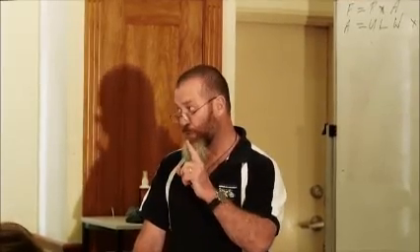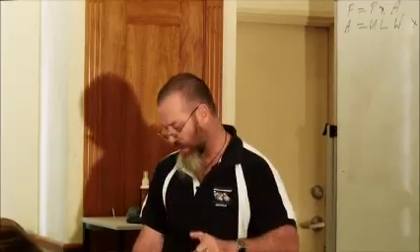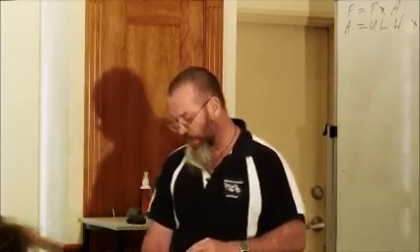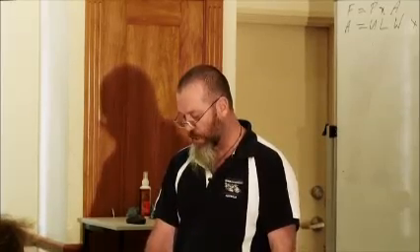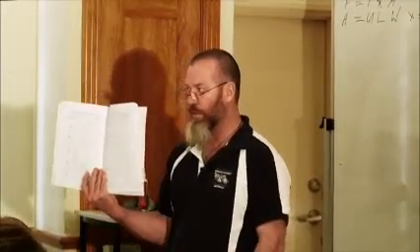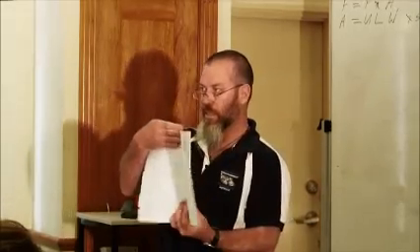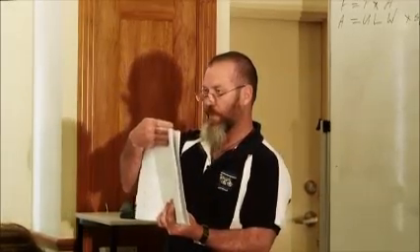Now, by way of example, for a tiled roof, and there's a couple of things here, I'm setting you up for a fall here, but it's so you learn. I want you to find a connection for me that will do 0.29 of a kilonewton. It's got to be equal to or greater than 0.29 of a kilonewton. So start at the top in JD5 at type B and see what you come up with. Okay?